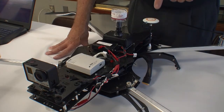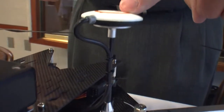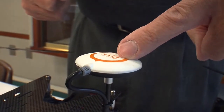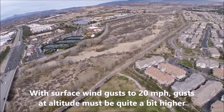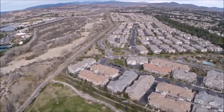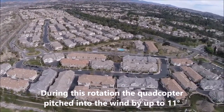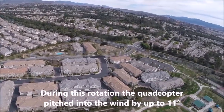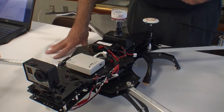When you get to the back, this is actually a GPS antenna and a compass, and that's used to stabilize the whole platform. So you could take this up to a given altitude, say park it at 300 feet, and now it'll stay within about a 10-foot box without having any other controls on it because it's controlled by the GPS. So it's a very stable platform. It'll remain airborne, depending on the instrument package you put on it, anywhere from 10 minutes to 30 minutes, and it'll take up to about a 3-pound payload.